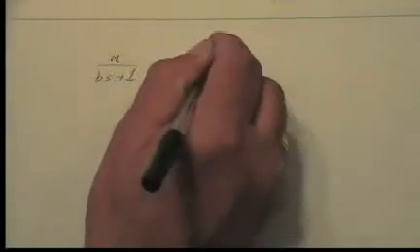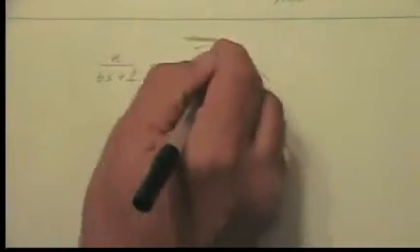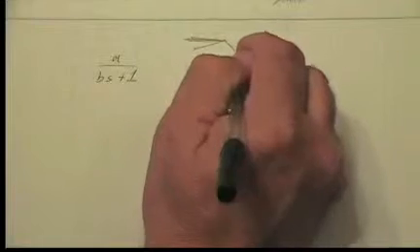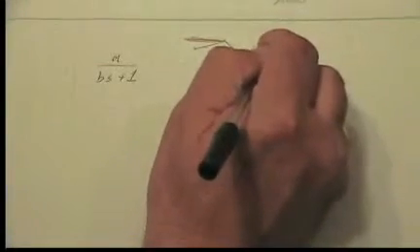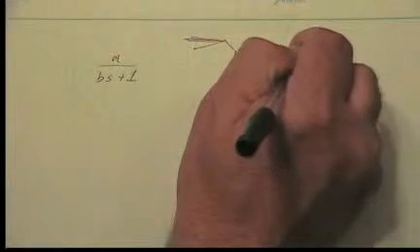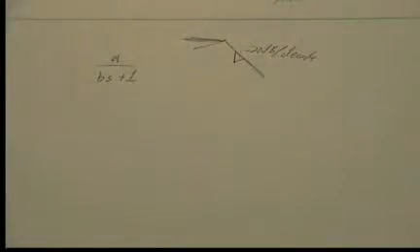And for a single pole, a pole right there, we would normally say that this declines at a rate of 20 dB per decade in the fall-off point. So this is the flat part, here's the decline. We would measure this and say minus 20 dB per decade. And by decade we mean some frequency relative to 10 times that frequency. That's a decade fall. It could be 100 Hertz to 1,000 Hertz. It could be 5 Hertz to 50 Hertz. It's all a decade. So that's what we're looking at.